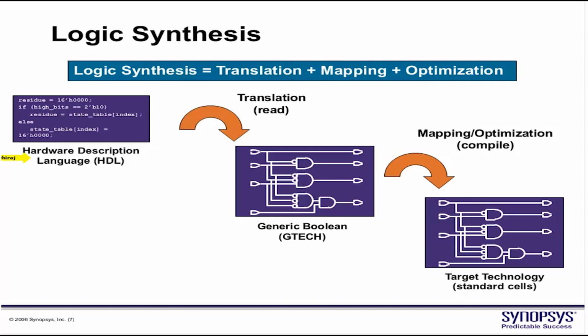So each technology node, for example a 90 nanometer technology node, corresponds to the manufacturing process where the channel length of NMOS and PMOS is 90 nanometer. So when we go for deciding a chip, we have to choose a technology node.